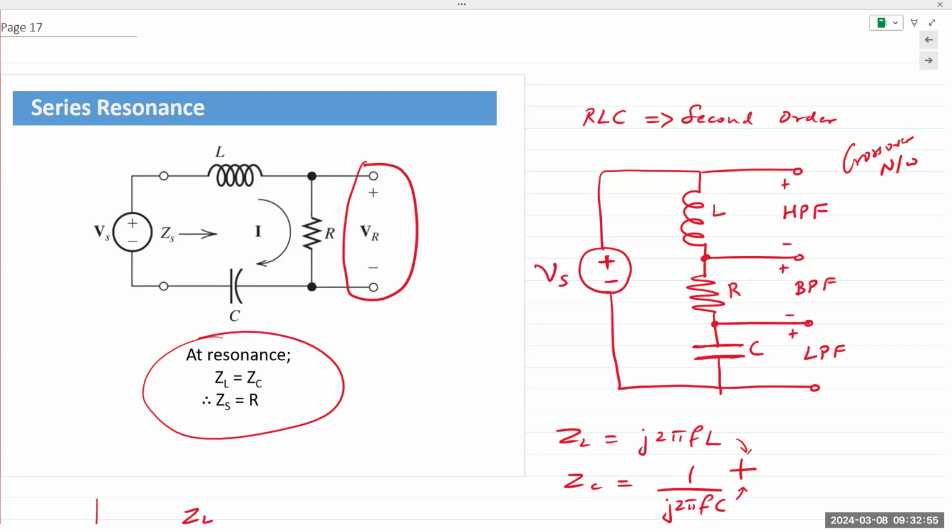And that's how you can actually take a single cable going into your speaker and split it up into 3 different parts. Okay. You've seen those 3 controls, right? Bass, treble, and mid. The mid is basically the band pass filter. This would be for the bass, and this would be for the treble. So a crossover network comprises inductors, capacitors, and resistors. At least the good ones. The cheaper ones would simply use capacitors and resistors.